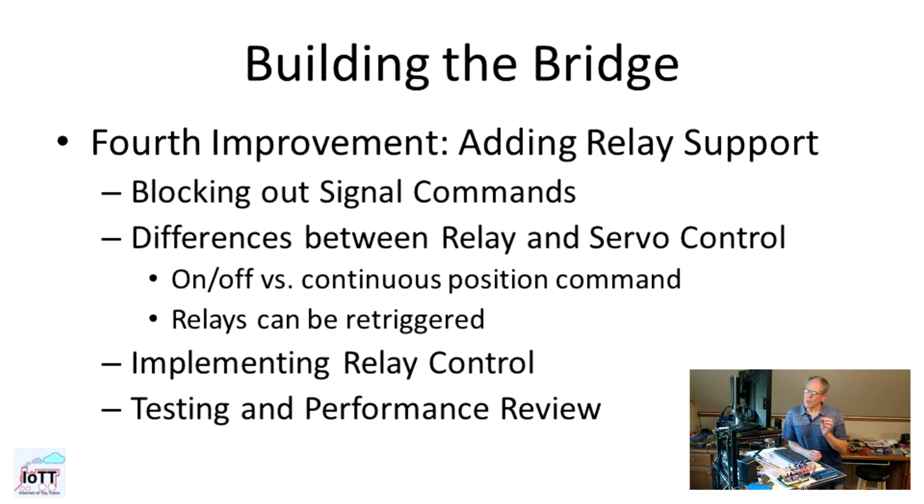And the other very important difference is switch commands actually can be re-triggered. If you have a slow motion switch machine that uses 4 or 5 seconds to go from one position to the other, and it's in the process of going there, and you send another switch command in the same direction, it can re-trigger that and make the activation time longer. And we need to somehow deal with that. So those, I think, are the most important things. Let's go back to our IDE and get that implemented.